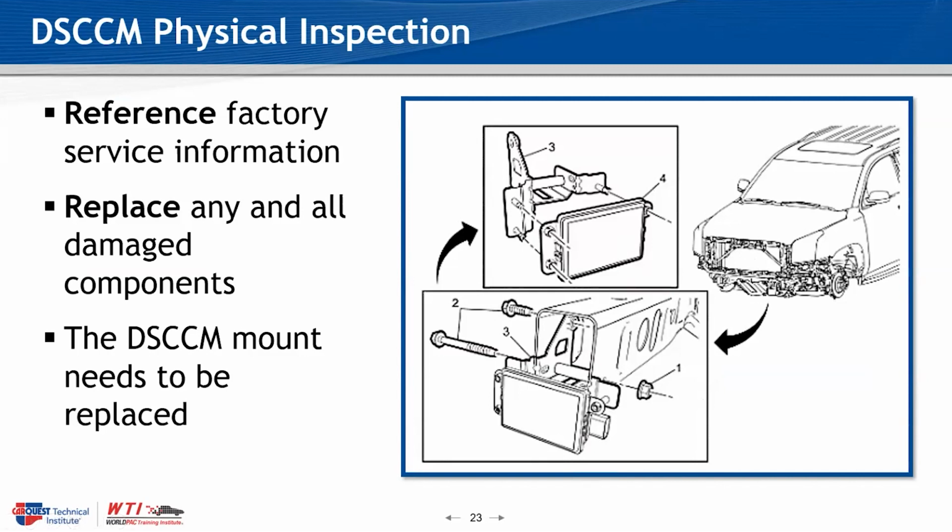The left front frame section that comes out was far off of its center line, looking down the frame according to the other side. Then I found some pictures online and determined that this is supposed to be pretty straight, and it was visibly not straight. So they had cosmetically repaired the vehicle, but underneath it was still ugly. And so at this point, I told them they're going to have to replace this front frame section, and then I would have to come back, or the entire frame.